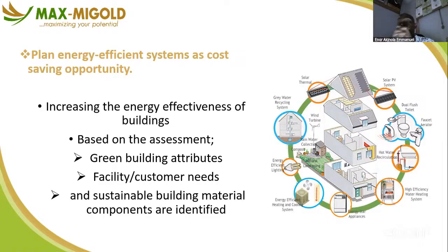Or possibly after you have conducted your assessment, you discover that the place is very good for solar. You can make the whole building a solarized panel instead of painting. Put solar panels on the whole building wall and use that solar energy generated to power possibly your common area within the whole facility. So you know that day in, day out, the common area energy is completely taken out of the net of the occupant. When you are telling your occupant that you are not paying for common area lighting, it saves them a lot of cost.